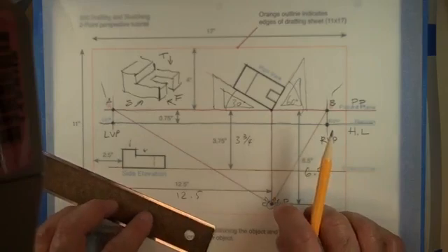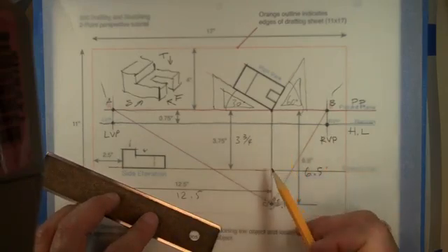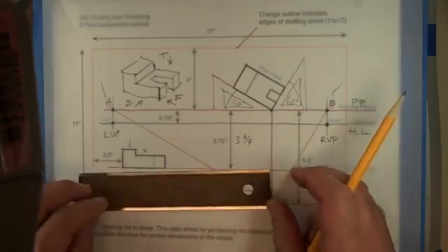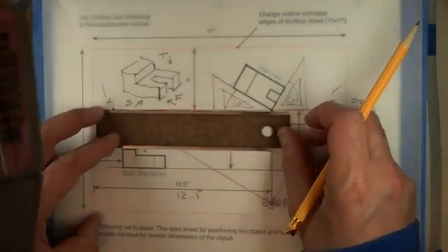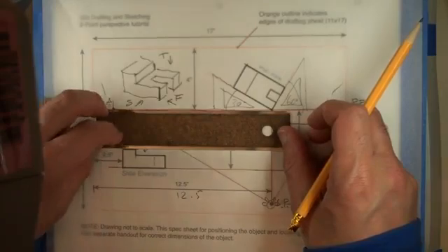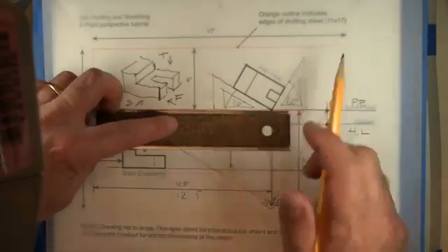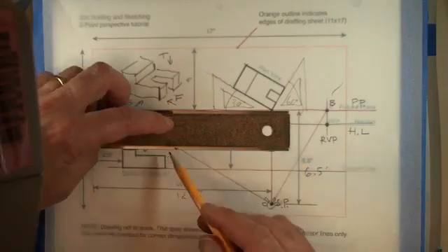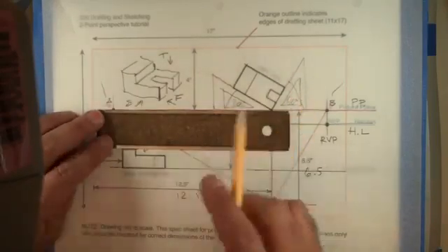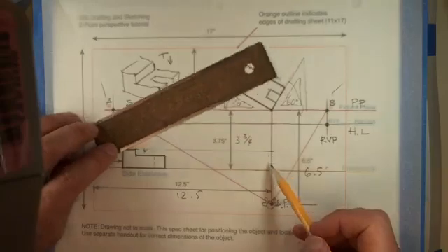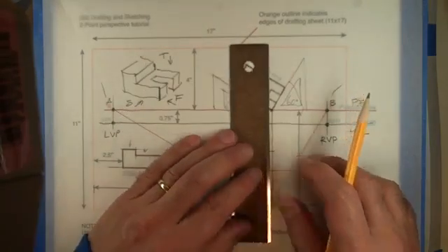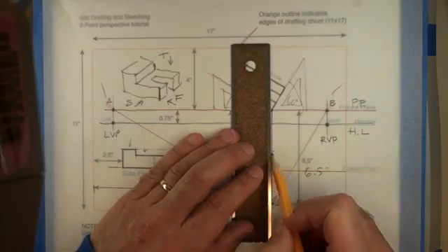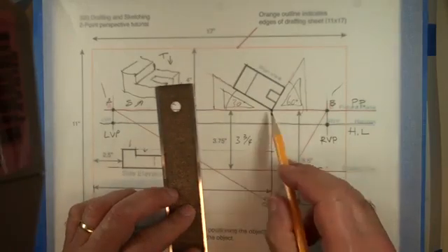The first step we'll do is find this line in perspective. Again, because it's touching the picture plane, it won't be in perspective at all, in the sense that it will be exactly the same dimension as the original. And what we'll do is we'll project the height of the object onto this line here, and that will give us the first corner.